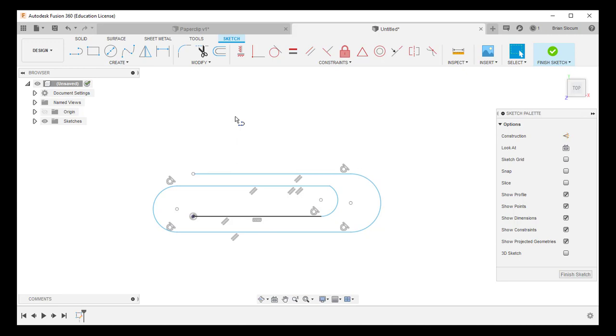All right. So really quickly, let's just examine what we have. We have this coincident relationship of the start of our line with the origin point. That's fine. That was pretty basic because we started on that line. We have this flat line. It's showing us that that flat line is horizontal with this indicator here. We have this tangency that happens between this arc and this line. That's good. This line comes up. We don't have that tangency here, right? We want a tangent at each one of those points.